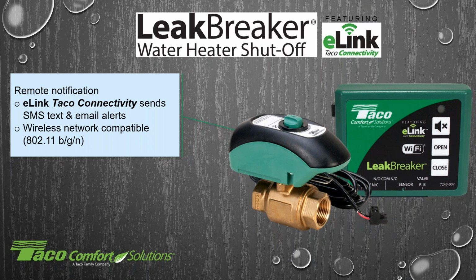I got a note from my buddy Rick, who said the CV of the valve was 32. Sorry, I was incorrect. I just had a different number in my head. So a CV of 32 for the leak breaker valve means flowing 32 gallons a minute through that valve will give you 1 PSI pressure drop. I think I saw a question also from Bill. It looks like we have a 3/4 inch valve. So yes, the CV of 32 of this device means a very, very low pressure drop.